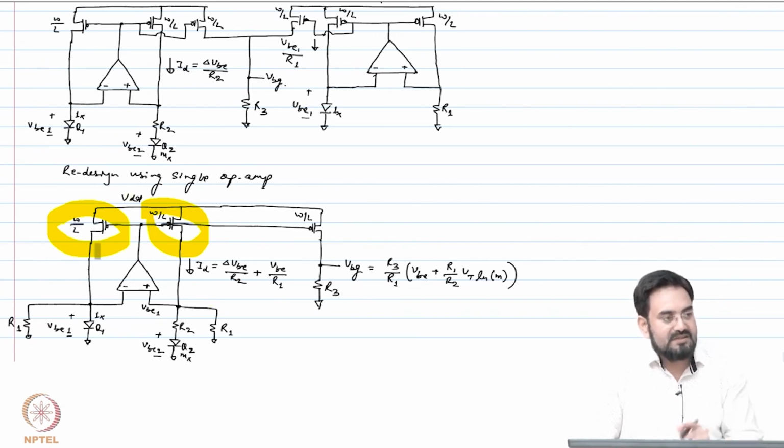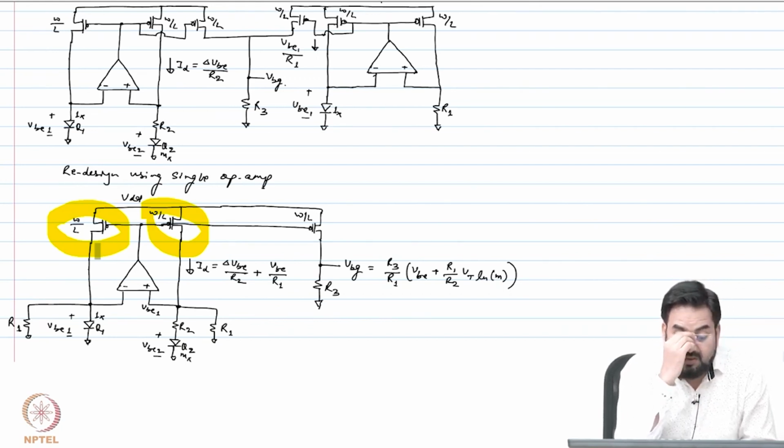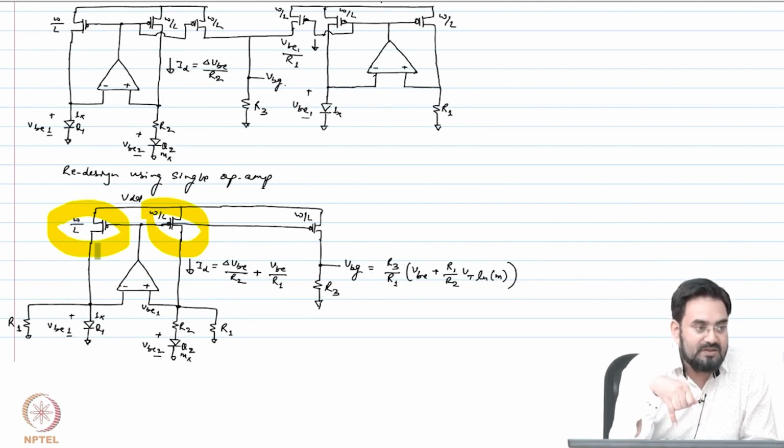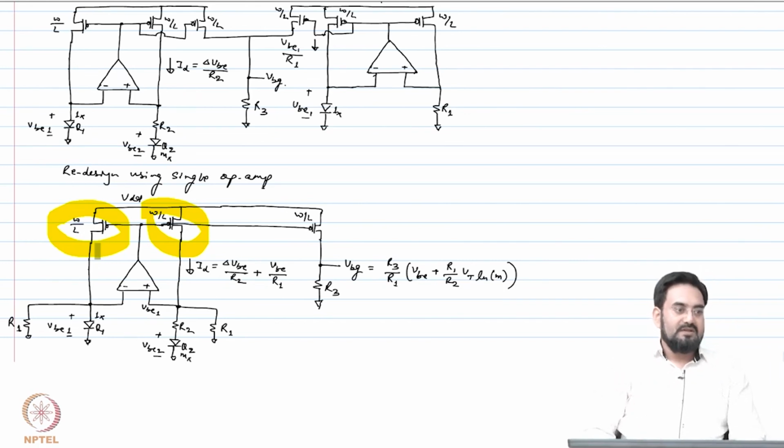So what you see, VDD minus VB is the VDS. So let us say VB is roughly 0.7 volt and your VDD is 1.2 volt. So both will see 500 millivolt. Okay. Now if your VBG is not 0.7 volt, if you design this for 0.7 volt, then they will be roughly same. Okay. But that will also be at a one particular temperature, because VB is a function of temperature, but band gap voltage is not a function of temperature. So you might see some variation, maybe plus minus 100 millivolt or so, but obviously it will be much better compared to if you use a different value.